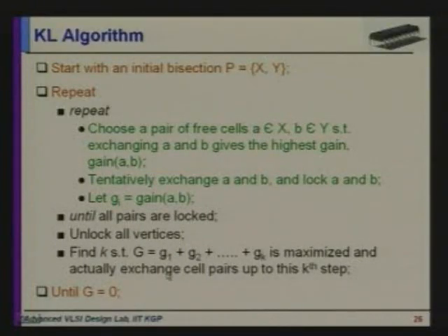So why do I do that? I just told you. Even if this gives me -1, after I have made this partition, I can get a vertex pair which again gives me good gain after this. And then I actually take up to that step G1, G2, G3, G4, even if there is a loss in between, or 2 losses, n number of losses in between, I find out up to the steps which give me the highest gain. Okay, right.